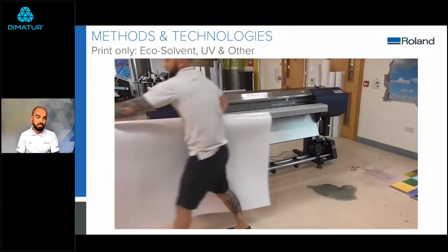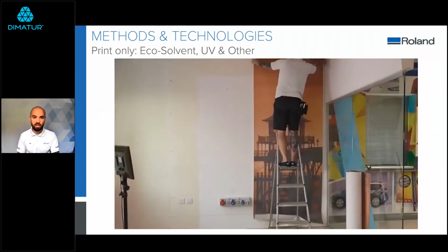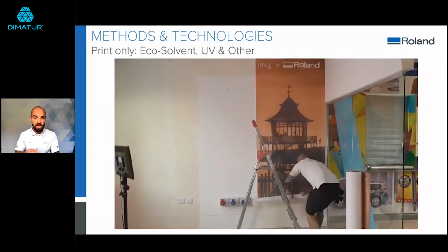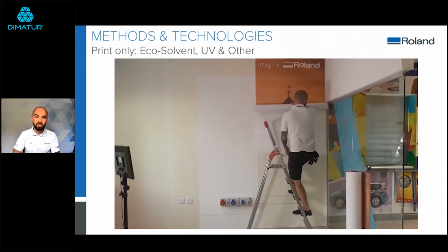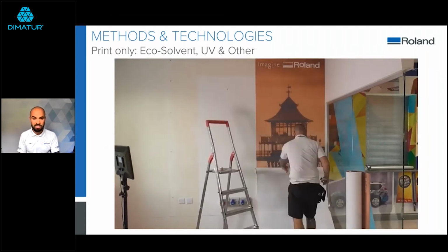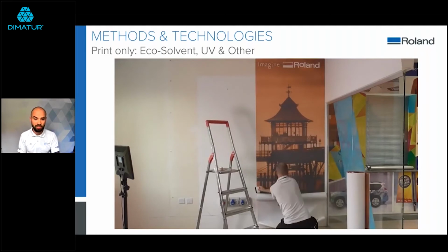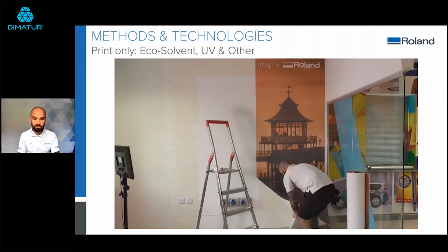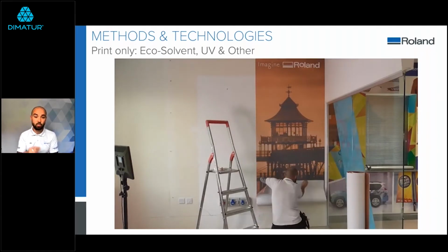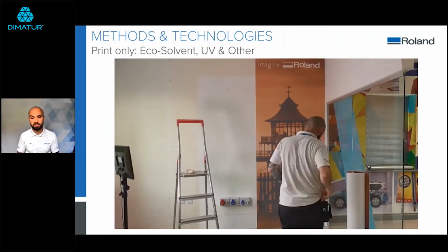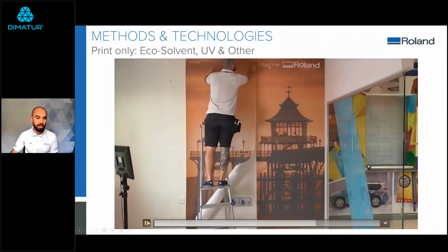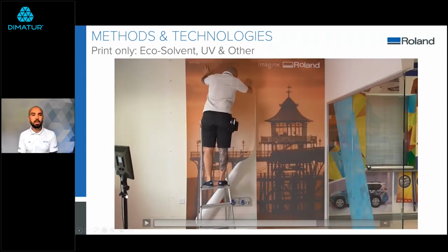So after they were printed, we just went and cut these down into the 2 tiles and started by, again, applying from the top in this example. It's again a really easy to apply material, just pulling off the backing sheet as we work our way down the material. In this example, we had 1 overlap, which was 20mm. So the overlap amount that you have, just going to pause there for a second, will depend on either the fitter or the type of material that you're using. So as a preference, whilst I was applying this one, I just wanted a 20mm overlap.